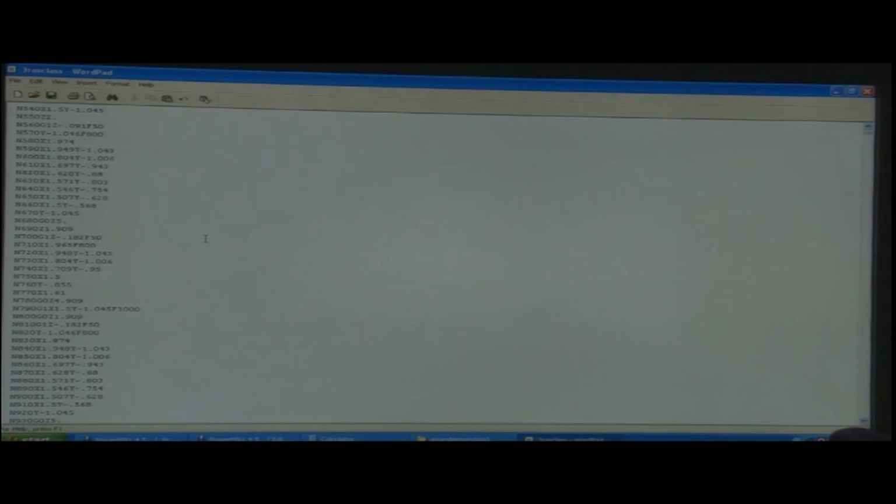For instance, if you have taken a FANUC program and we are trying to put it on a different machine, we have made the program for a specific kind of machine, and the same program is to be exported to another kind of machine. For that kind of machine, a different setup in the beginning and at the end, different commands are put. However, the major machining operations would remain the same most of the time. So, these are the major things.